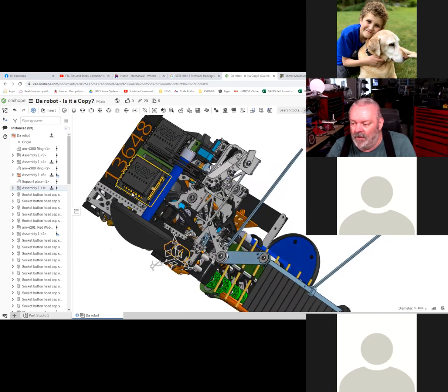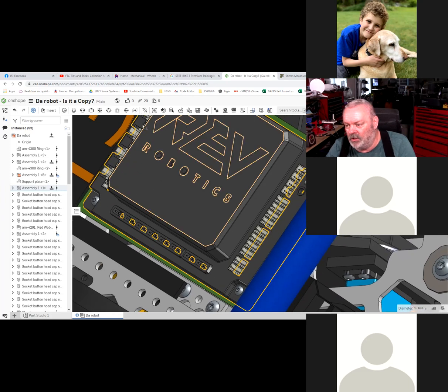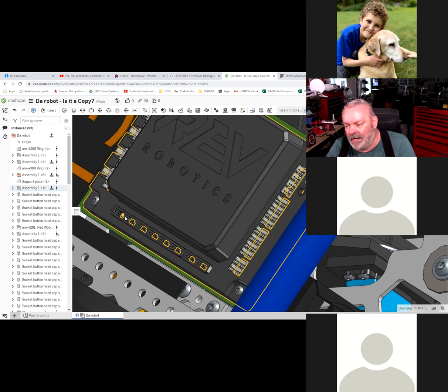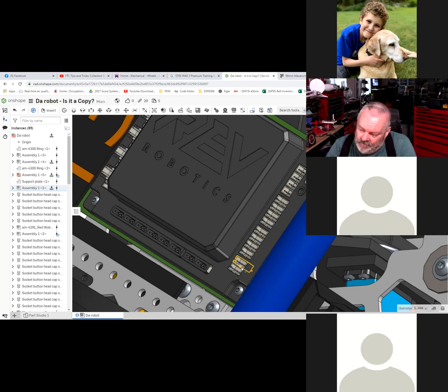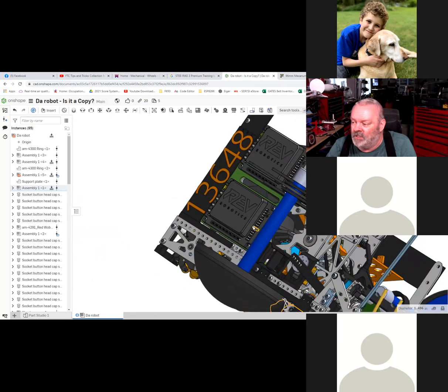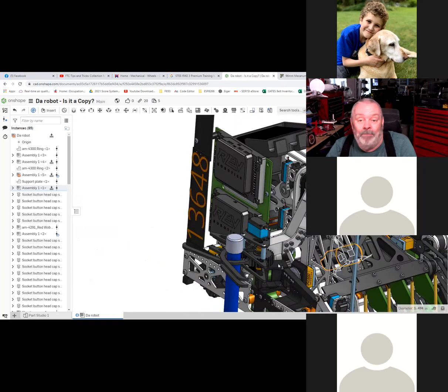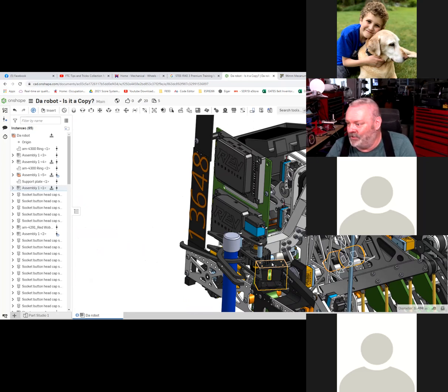What that did is it gave him more ports. The control hub controls 4 DC motors and 5 servo motors, and it has a set of analog to digital channels, some digital channels, and some other communication features. By having 2 of these, he's able to use 10 servo motors and lots more switches. He didn't actually use that many servos, but you can load up on a lot of servos here.